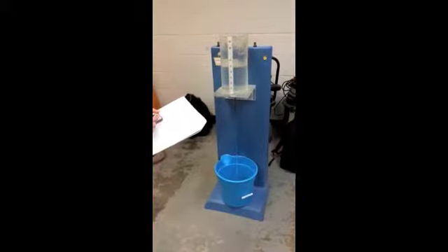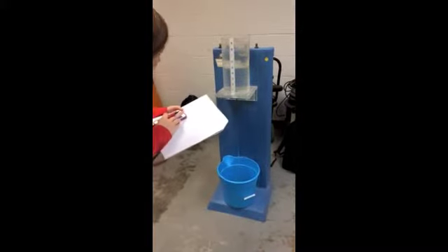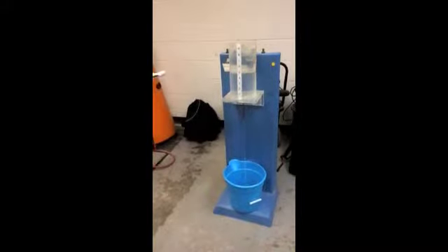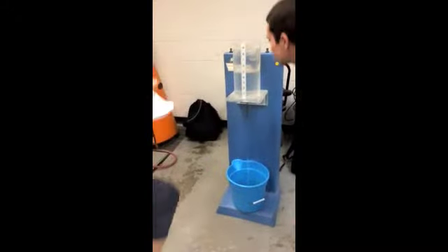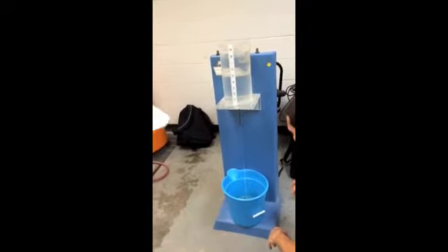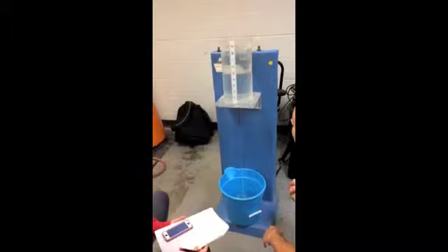The tank was filled with water and it was allowed to flow freely until a certain point was reached before a vortex formed. That time was recorded. The same procedure was done 5 times and the highest and lowest measurements were discarded and the remaining were averaged.